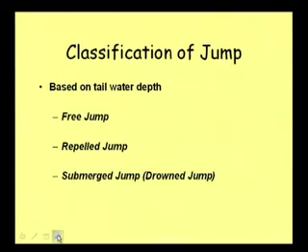Of course, some graphical procedures were developed and some approximate solutions were also developed. In fact, we also tried to develop one approximate, empirical solution, generating a lot of data in a laboratory channel, and then also by computation through a mathematical model we developed a lot of data for y1 and y2. We then tried to see how this can be related empirically, and we could relate it based on the discharge value. Of course, this equation is valid for a definite range of channel, maybe at the level of an irrigation canal, but we cannot say in general. That is why I am not putting it here. Anyway, these relations can be used.